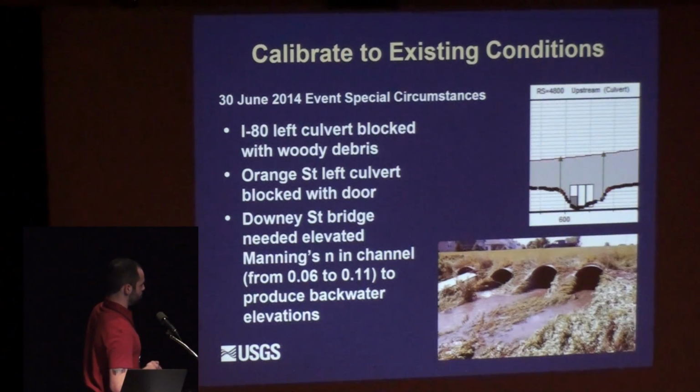And also, there's this Downey St Bridge on the Hoover Creek that had elevated levels and backwater behind it. And I had to adjust the channel Manning's n in the channel from 0.06 to 0.11 just to get the water level up high enough behind the bridge.